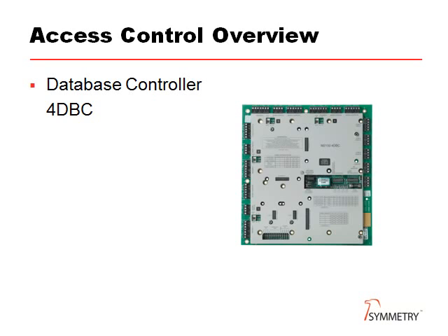So let's see how we would create a typical access control system. The database controller, or DBC, is the heart of any expandable access control system. It holds a database of cards, as well as information on which cards are allowed through which doors at various times. I use the term cards here in a generic way, as the credential could be tags, PIN numbers, or even fingerprint data.